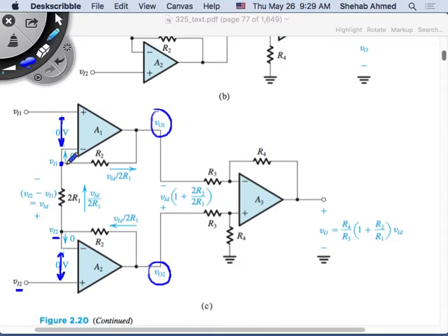Now, what is passing through to your difference amplifier? That's what we want to see, okay? Because the limitation of the previous circuit was that we were amplifying the common mode signal as well. So now let's see what's happening to the common mode signal.